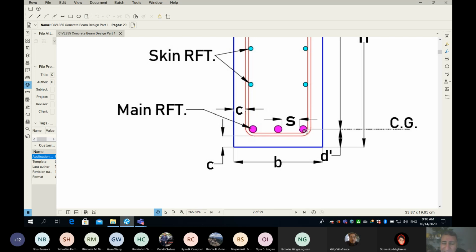And then we have at least, look at this please, at least 2 bars, because every corner of a beam needs a bar, which means minimum 2 bars. And between the 2 bars, there should be a spacing because it allows concrete to flow. If you put all this in one package, you will know I cannot make my beam 50 millimeter. Say minimum cover is 30, so 30 plus 30, that's 60. And then stirrup 10 millimeter, so 60 plus 10 plus 10, we are at 80. And if I add 20 plus 20, that's 40 plus 80, it's 120, and leave some spacing.